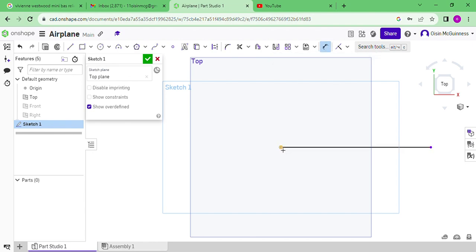So this is the new way of dimensioning. Instead of highlighting this line, just clicking it like we've been doing, I'm going to press escape on my keyboard so that dimension isn't highlighted anymore. I'm going to press point to point in order to start dimensioning. So I've just selected the two points that make up that line to dimension it. So I'm going to put this down as 145.